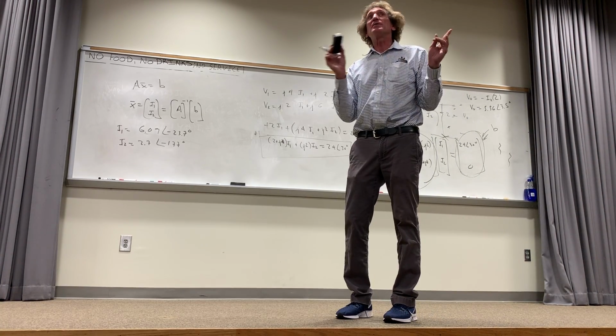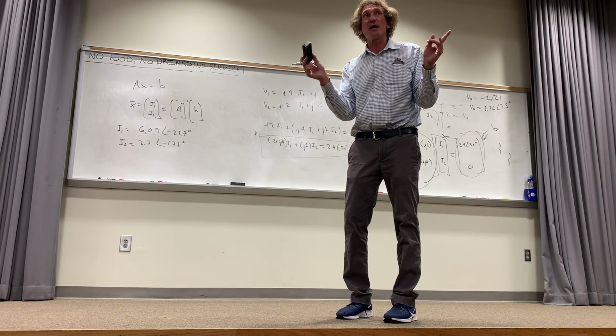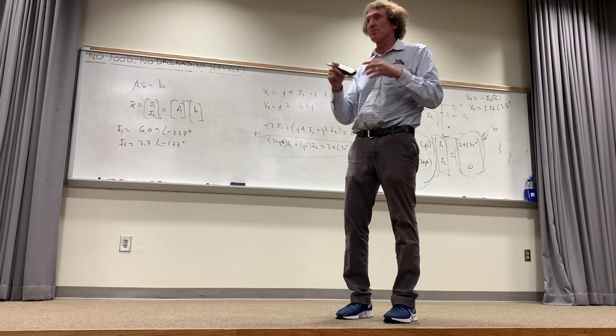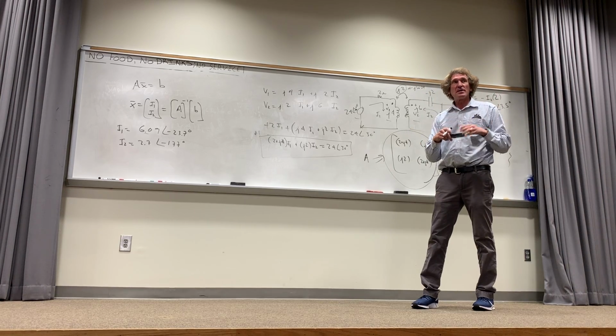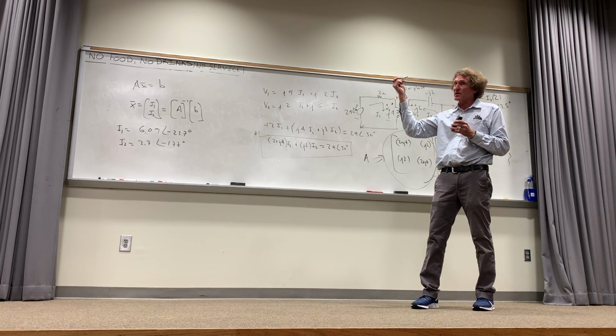The internet has a whole lot of different ways to do this with different standards. This is the common standard in real electrical engineering. Currents flow into the dotted terminals. The equations that I gave you: V1 is equal to j omega L1 I1, where I1 is flowing into the dot, plus j omega times M, the mutual, times I2.